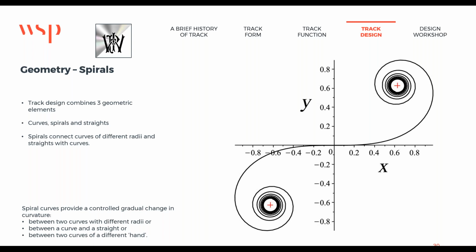A Euler, sometimes called a clothoid spiral, directly reverses about a point where the radius is calculated as infinity. In other words, where the versine reading is 0 millimeters and the track is momentarily straight. So if you were to measure the versine at that point by stretching a chord across there, you would get 0 millimeters as the offset. It would be a straight.